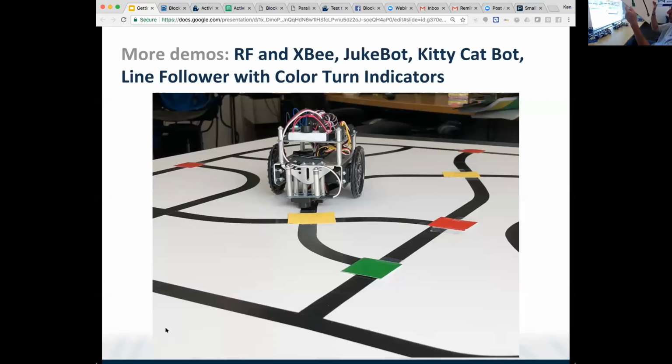Green means turn around. And the robot that I'll place on this is a standard ActivityBot 360 with a QTI line follower circuit and a ColorPAL in front. And this particular program consists of real-time speed control based on the line follower sensors, and then when it sees a color, it switches over to dead reckoning to turn right or left. Earlier, this was getting a little bit flooded with my lighting coming in from the outside. So let's give it a shot. I'll close that blind for us.